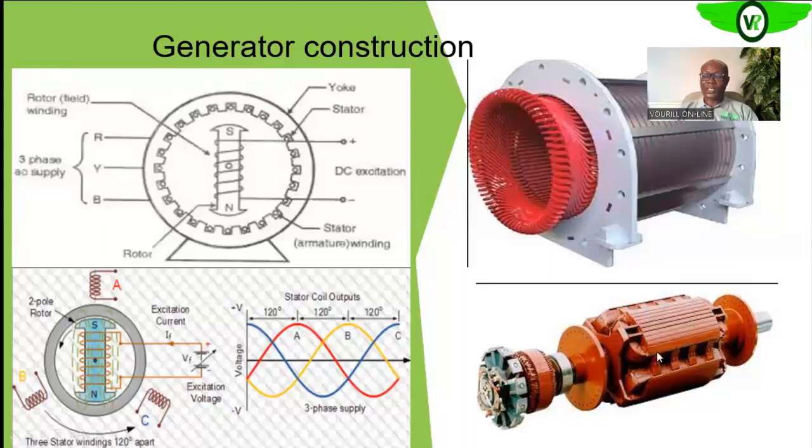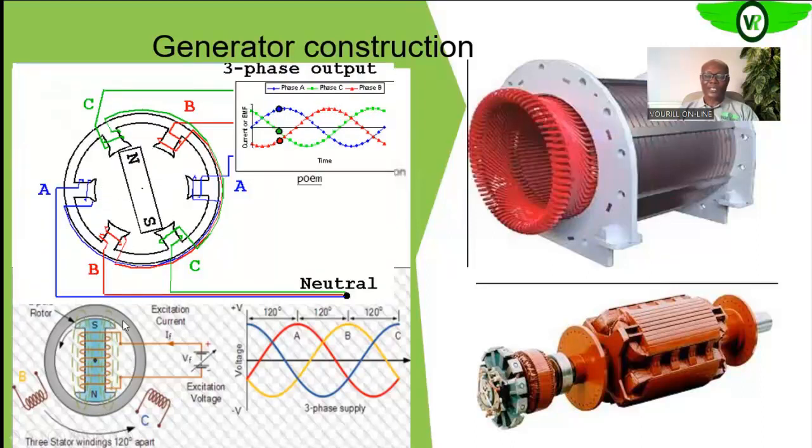So on your screen now, this is the rotor. This one is carrying the field windings. This is the exciter armature, okay, which produces the EMF that is sent to the field winding. So as the field is rotating within this, you see that since the field is cutting across all of these conductors that make up the A, B, and C phases, voltages are induced into those conductors.